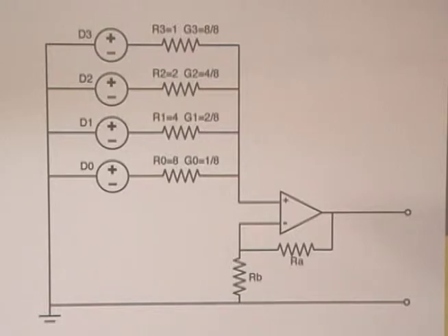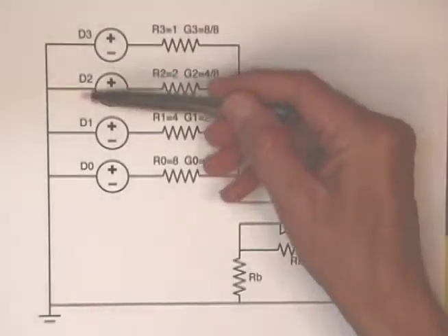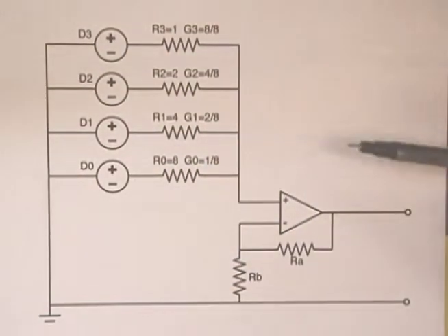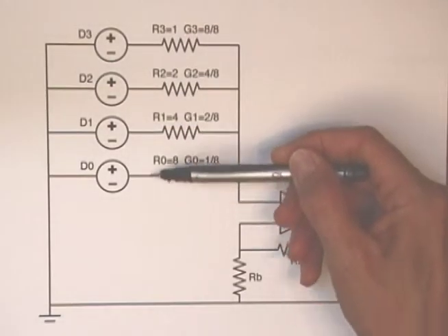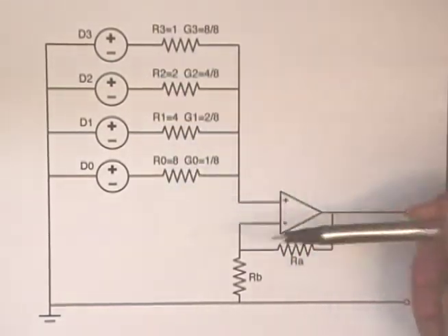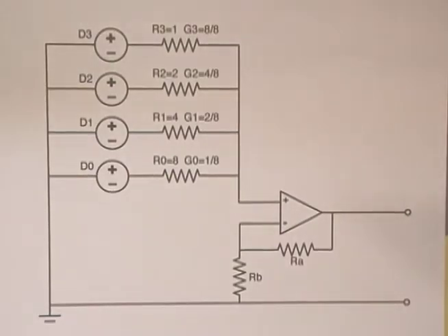The third and most important area for improvement has to do with the input stage. This converter shouldn't have to know the value of incoming logic 1 and logic 0. Instead, it should implement the static discipline and implement reasonable values for VIL and VIH that the downstream device can handle. Then it should condition the inputs internally to have the appropriate voltage levels for the rest of the circuit. We'll address that in the next tutorial.